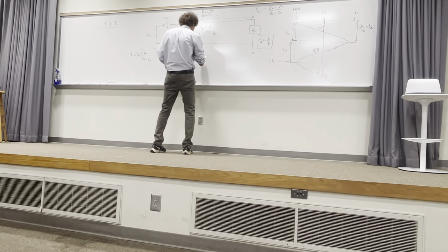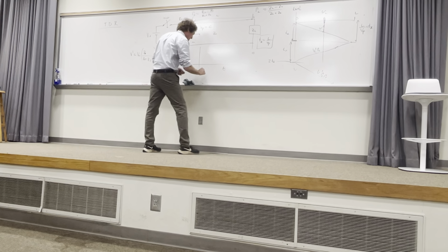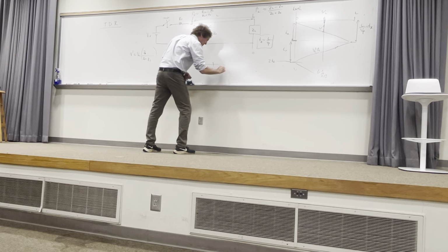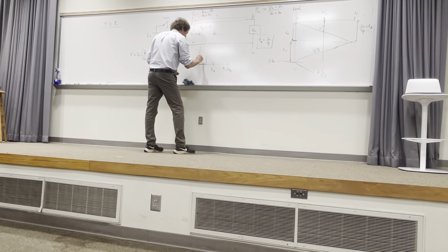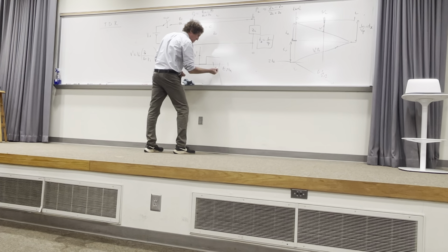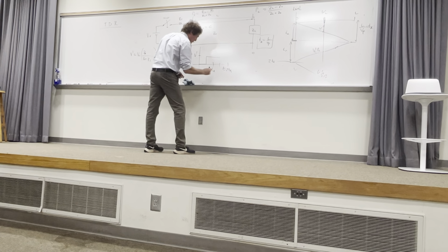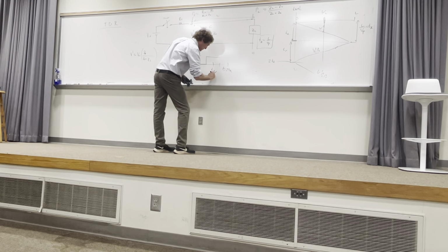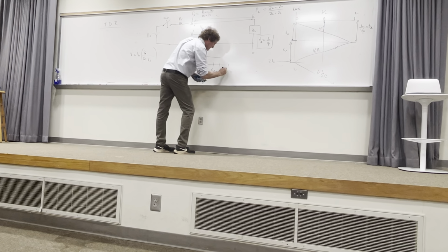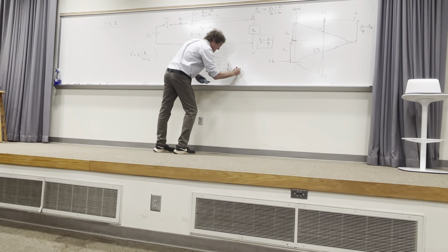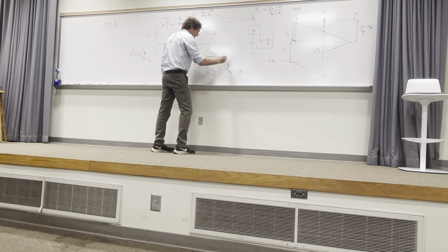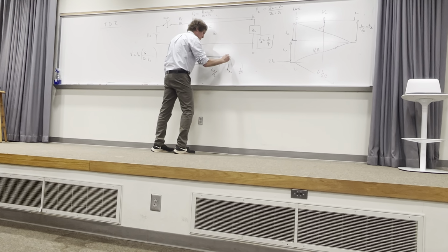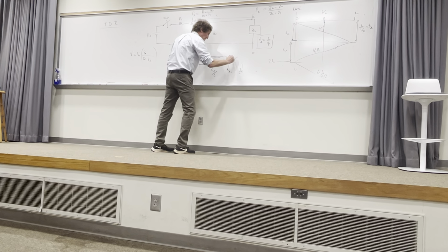So what it would look like, if this is time, and this is T line, it's 0, then it hits this point. Now it goes to whatever V prime is. Keeps going, then when I hit this point, this is actually T line over 2. And this should be T line, I'm in a hurry now. And this would be 3/2 T line. Then it's gonna stay there, then it's gonna hit this value, and now you're gonna add something, basically the reflection coefficient at the load plus 1 times V prime, and you're gonna keep doing it.